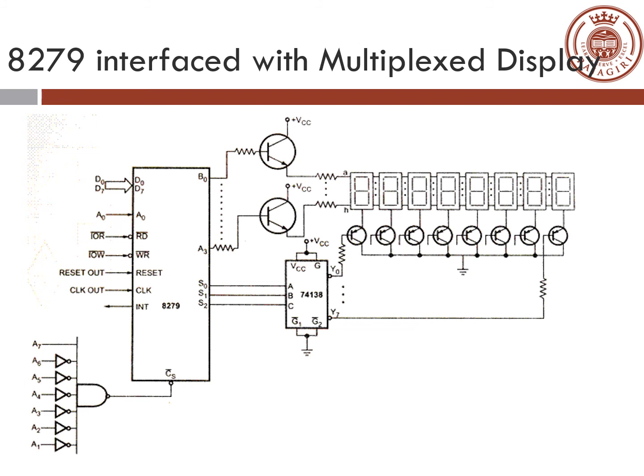So we use the display outputs A0 to A3, B0 to B3 to control the 8 LED display. These 8 outputs are used to drive the individual segments of the 7 segment LEDs.